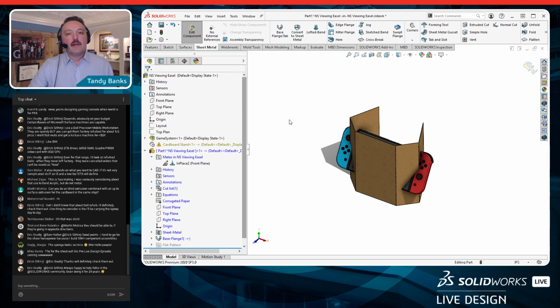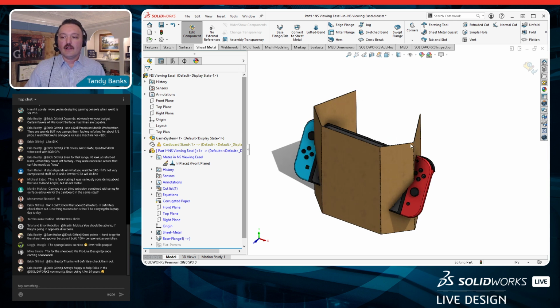But again, if you've never heard that before, good rule of thumb whenever you're doing part geometry is to add all your material first. So that'd be extrudes and revolves and sweeps and those kind of things. Cut away material second, do your subtractive processes, and then use edge conditions like fillets and chamfers as a tertiary effect there. If you'll use those, really good best practice to give you a lot of success in running SolidWorks.